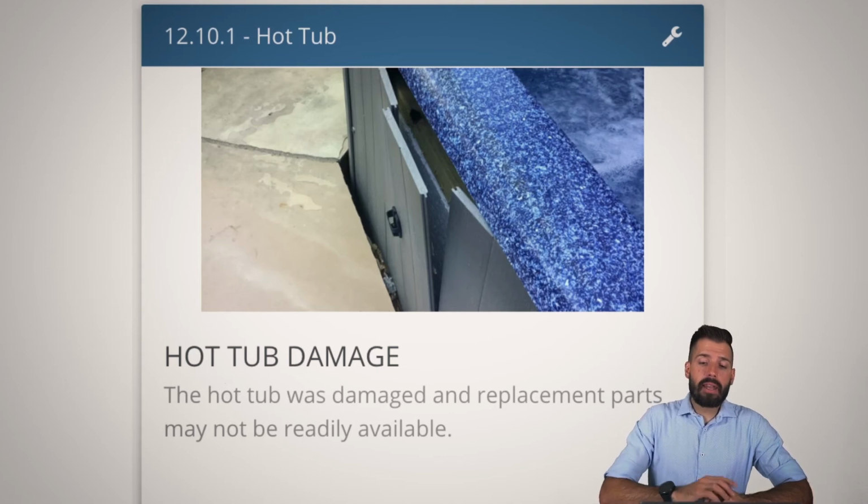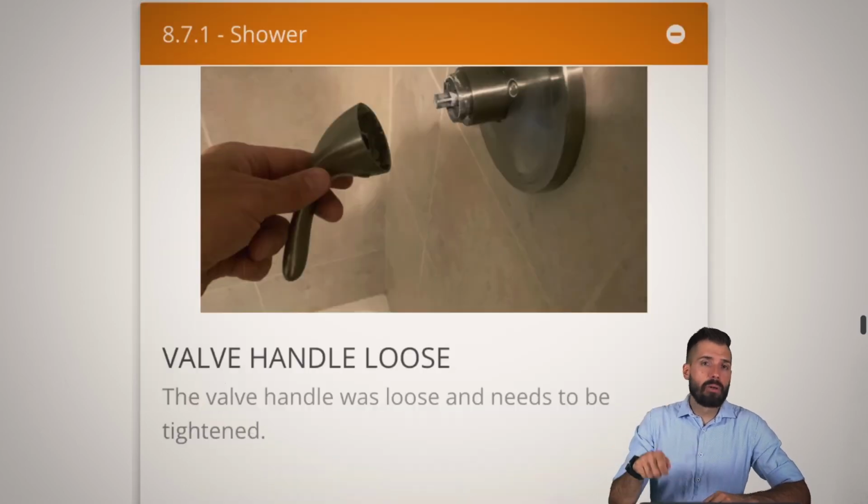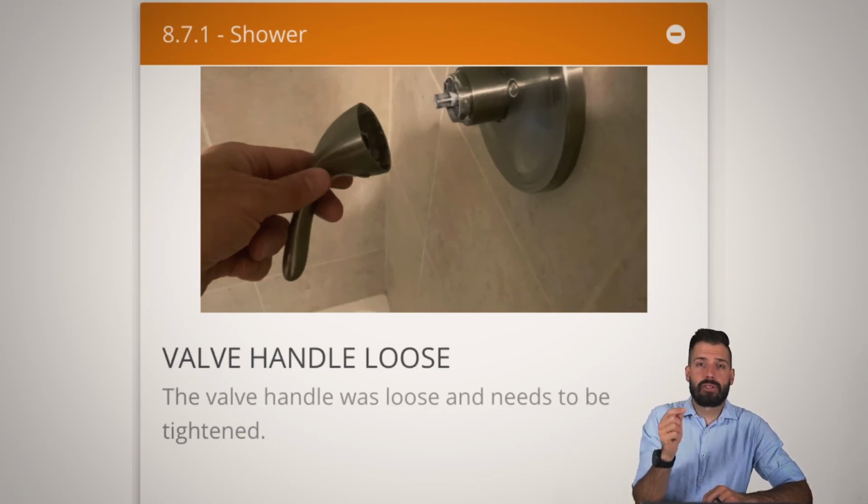All right. A lot of these things, same with casement windows and other things like that, you have a handle that can come loose. And that's because there's a little set screw and you need a small little special screwdriver just to be able to tighten it up.